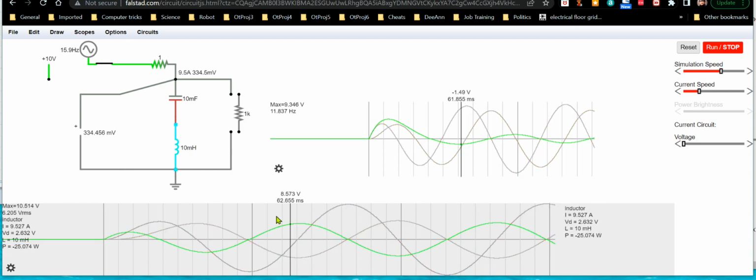It's just that right now the voltages are approximately equal because it's at resonance and they're the same kind of component character. So if one of these was 1 microfarad and this was 10 millihenry, you'd see something totally different. But since these are both 10 millifarads and 10 millihenries, everything looks like you might expect it to. But again, you get two voltage waveforms, and the current waveforms are in phase.